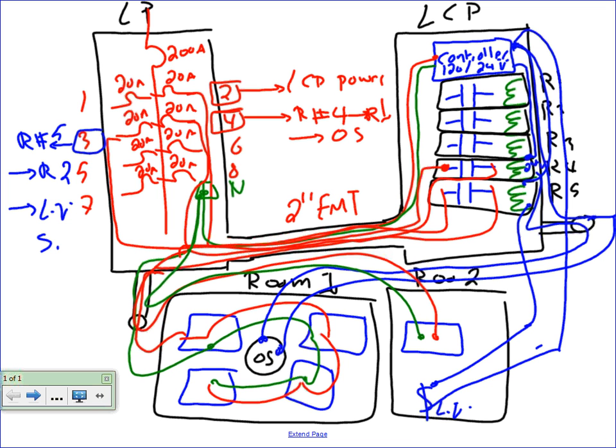Same thing. I went to the controller, back into the relay. So what happened when you turn a switch on and off? When you turn the switch on, you provide a 24 volt across this coil, and that coil will energize, in turn drive, bam, bam, drive the lower one to close, and your light in room number 2 is on.